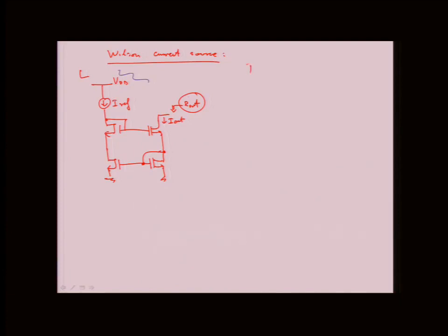So let's say type of feedback. Maybe the first thing would be to see which transistor is really the controlled source, so to speak. So let's label them M1, M2, M3, or sorry, M2. Let's be consistent. Okay, so which one really represents the gain?